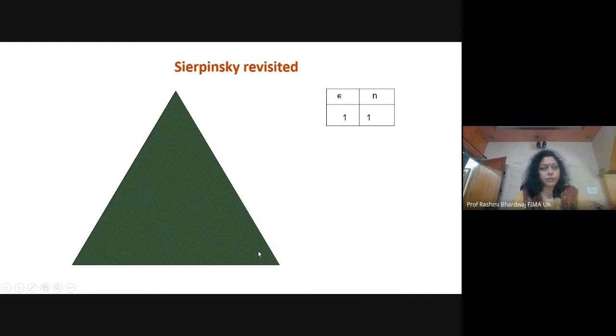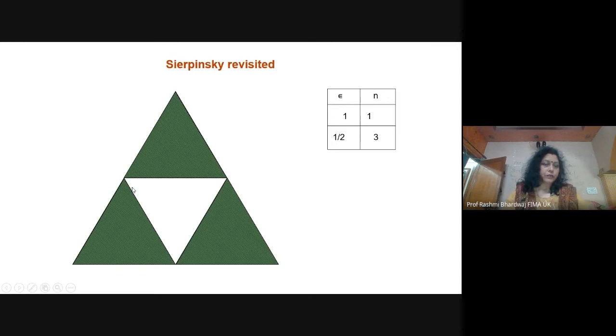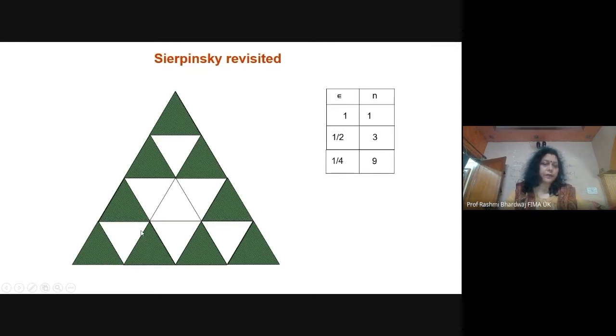And this is, I can say, the most important one, the Sierpinski triangle, because now everywhere we are using this Sierpinski triangle, and it is very helpful because nowadays we are using a fractal antenna in our communication systems, and this fractal antenna is nothing but based on this Sierpinski triangle. What we have to do, we join the middle points of the triangle lines and remove that part. So when you remove it, 3 triangles remain. Again join this and do that.